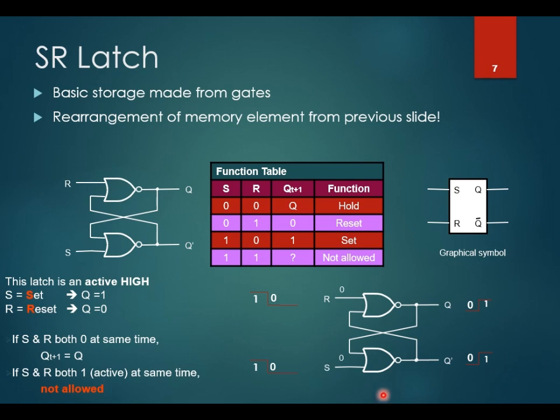Even if you keep the 0, 0 at the input side, which is supposed to mean hold in the correct functionality, because of the previous signal 1, 1 we assigned, the continuous 0 here will not play the role of holding Q. Instead, the continuing 0, 0 will keep toggling the output Q and Q bar, and it generates the race condition.